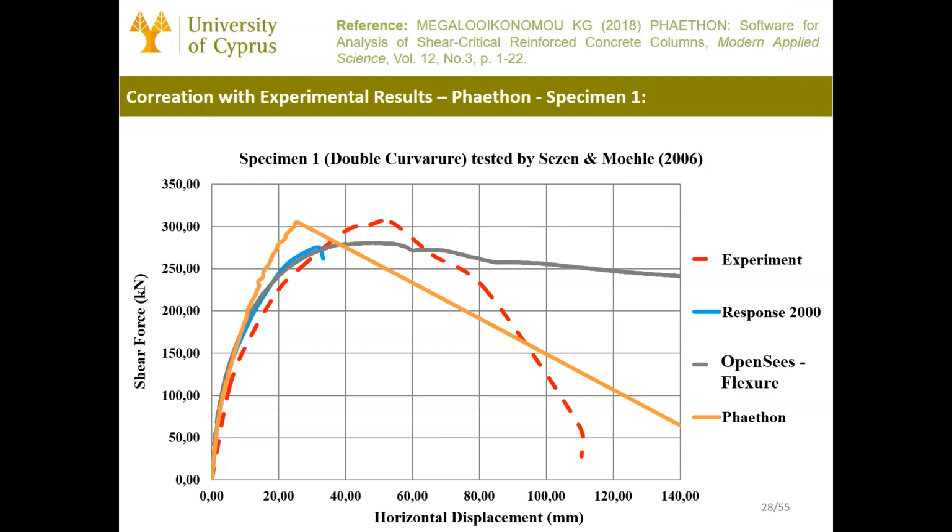Okay, you mean the model and the experiment. In OpenSees, you didn't consider any limit state material model? No, exactly, not any zero length. The reason I did that is that I want to show you that the software available for design usually models only this flexural response.